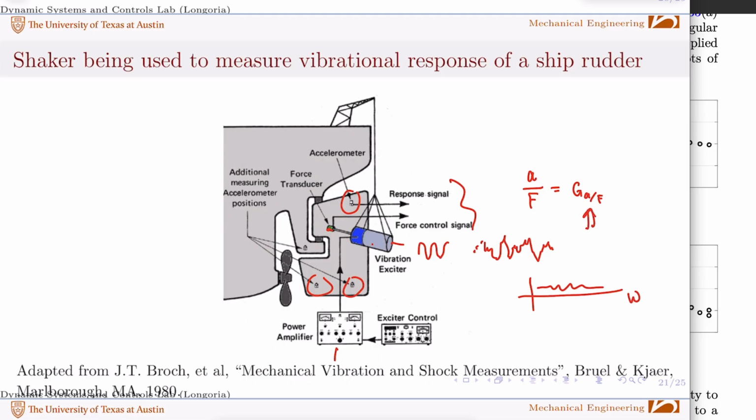With sinusoidal testing, you go frequency by frequency, right? You get data at one frequency, and then the next one, and the next one, and you march through the frequency range. By using other kinds of signals, like random, you're using Fourier transforms and spectral analysis, building transfer functions almost across the whole frequency range of interest.